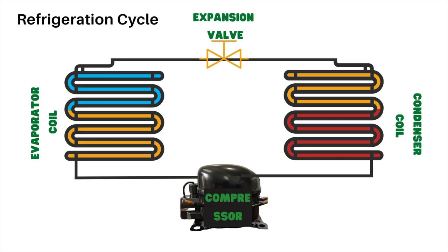The boiling temperature of refrigerants is typically very low, so do not think it needs as much heat as regular water needs to boil. So they have a very low boiling temperature. That's why this coil is called the evaporator coil, because the refrigerant inside it starts slowly evaporating as it takes the heat from the room and absorbs it in its own body. At the end of stage 4, as the refrigerant leaves the evaporator coil, it's now low pressure warm gas, no more liquid. This low pressure warm gas is now sent into the condenser again, and the cycle starts all over.